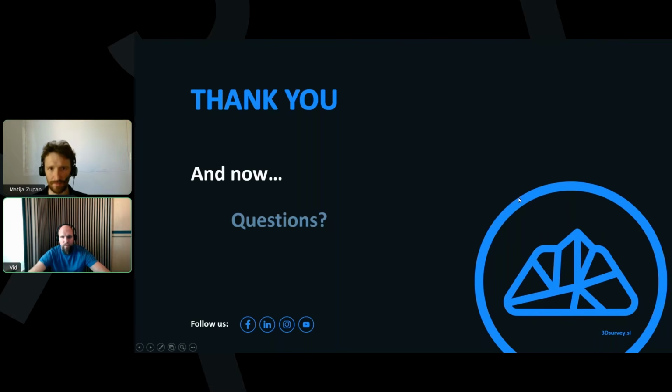Yeah, because while you are recording, the SLAM is just quickly showing you what you have mapped, basically drawing a map of where you are with the scanner. This helps you know what you've mapped and what you haven't. But in order to make the data very accurate, you need to download it onto the computer and put it into their software. Each SLAM scanner comes with this software, and that makes it more accurate. It calculates more accurately how you were moving with the scanner when you were doing the scanning.